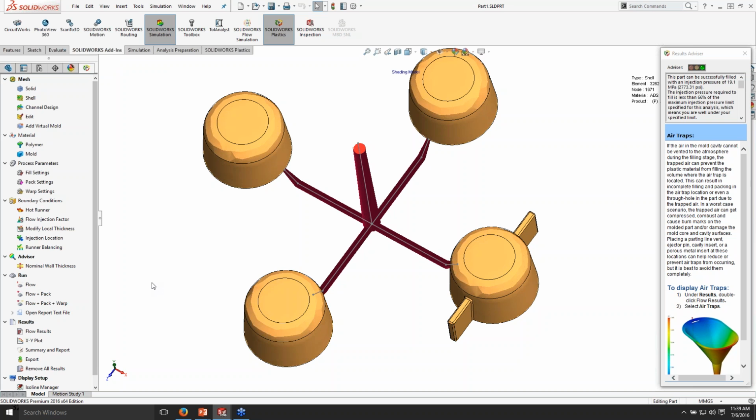So to chime in a little bit, as Shaun was running the simulation, this was very close to the same issue that I had with one of my customers currently, where they had 3 parts that were identical, and then one that was slightly larger in volume, not much. Very similar to what you're seeing here. The reality is that as injection molders, with fill weight and fill balance, close isn't good enough. You have to be very accurate, because if you're not, you can have flash on one part and short shots on another part. So fill balance is extremely important.